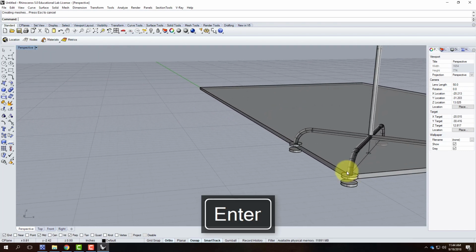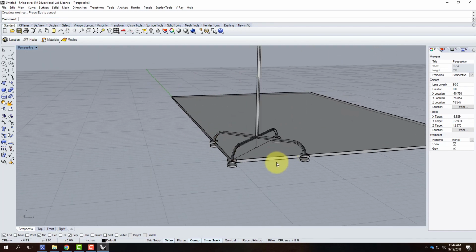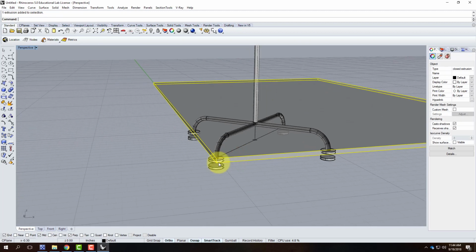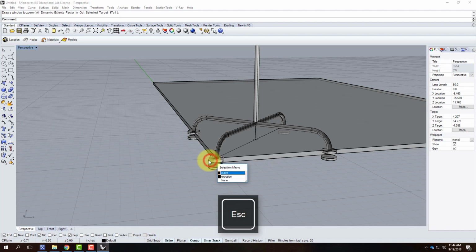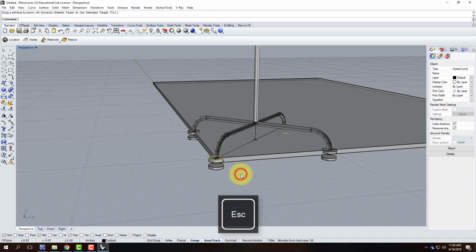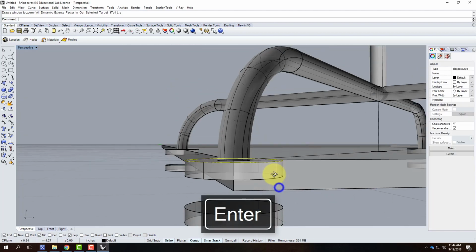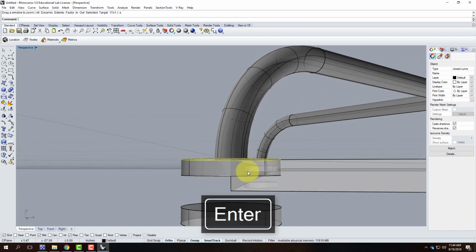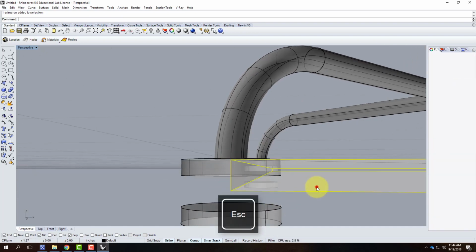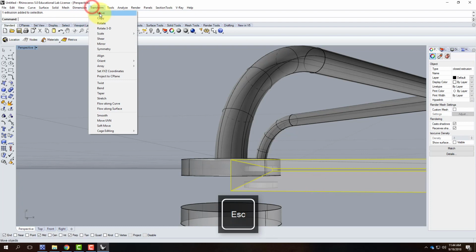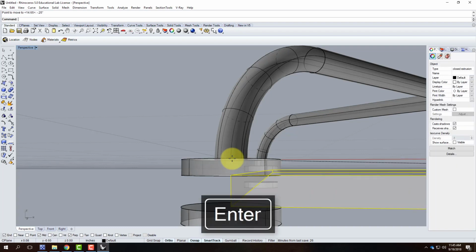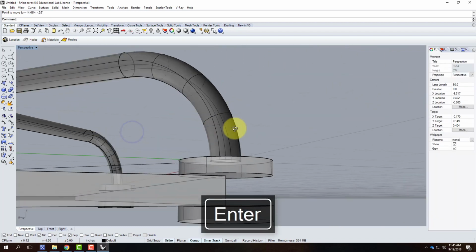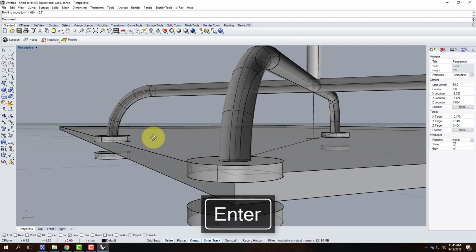And there it is. It looks like when I did it, I'm not quite low enough. Hold on one second. Let me show you this. When I created it, it was at 0, 0. It needs to go down by another 1/2 inch. So let me go ahead and go to Transform, Move, Vertical. This is going to be -0.25 inches. And there we go. Now it's in its correct position.